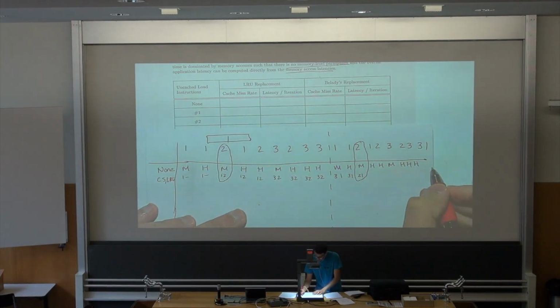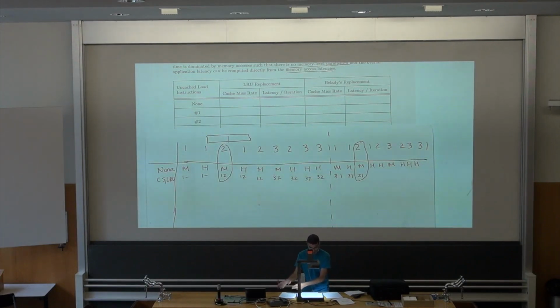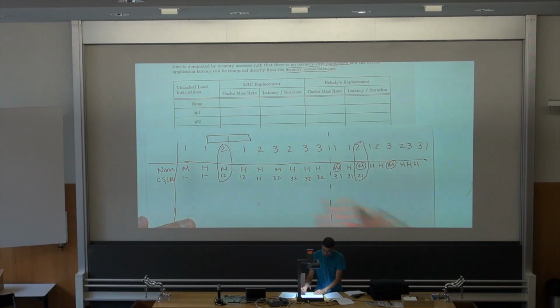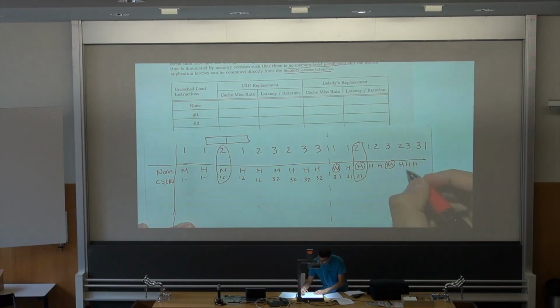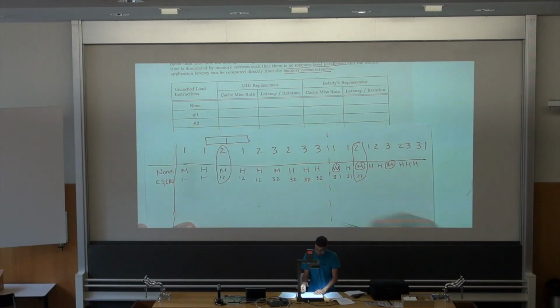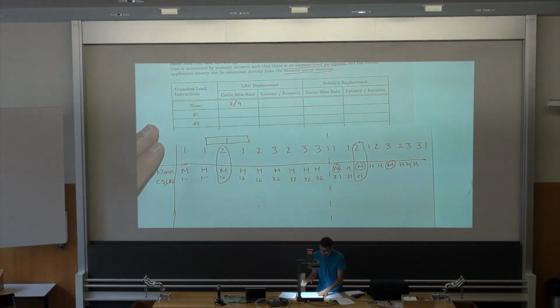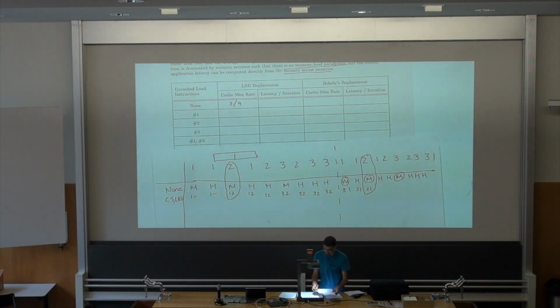And so from this, we can see that in this, which represents the steady state operation now, because this pattern will just repeat over and over, we have exactly 3 misses, right? So our miss rate in this configuration here is 3 out of the 9 different accesses that comprise this iteration, right? So here the cache miss rate is effectively 3 out of 9. Okay?